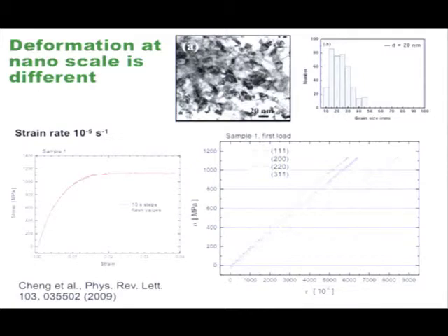And if possible, you like to use complementary techniques, perhaps high-energy X-ray and so on, to look at different parts of it. In fact, especially for these deformation studies, if you use two techniques and bring them together, that can really help you decipher what's going on. The example that I showed on nanocrystalline nickel, this is actually high-energy X-ray data, I have to point out. We have neutron data that shows a similar thing. So those two things come together and give you a better answer.